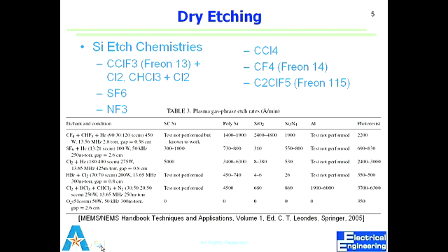So I can easily calculate the minimum photoresist thickness I need. And you'll be glad to know that we always have a much higher thickness of photoresist once we do lithography, if the feature sizes are not very small.